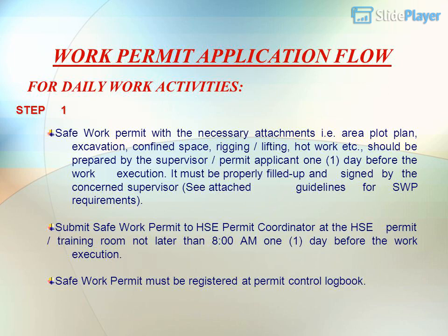Work permit application flow for daily work activities. Step 1: Safe work permit with the necessary attachments, i.e. area plot plan, excavation, confined space, rigging, lifting, hot work, etc., should be prepared by the supervisor, permit applicant, 1 day before the work execution. It must be properly filled up and signed by the concerned supervisor. See attached guidelines for SWP requirements.